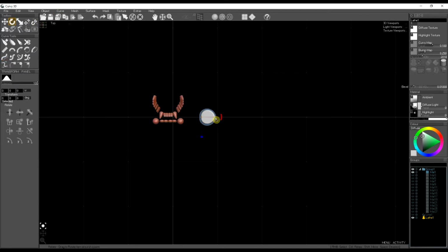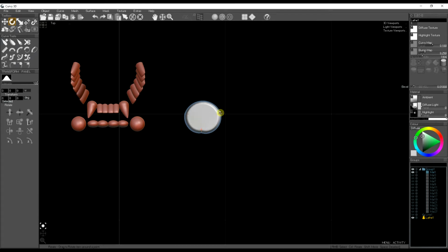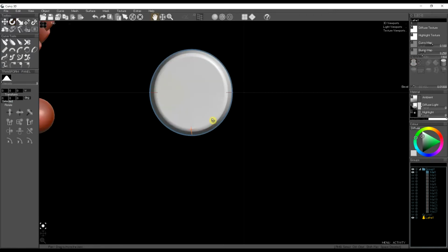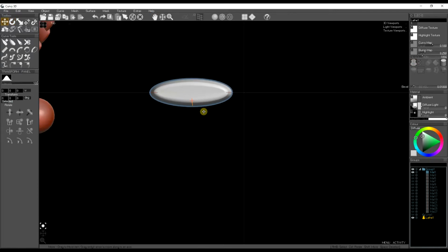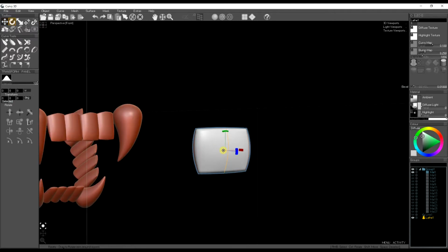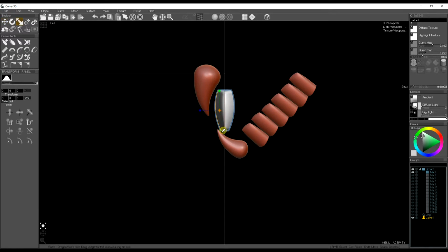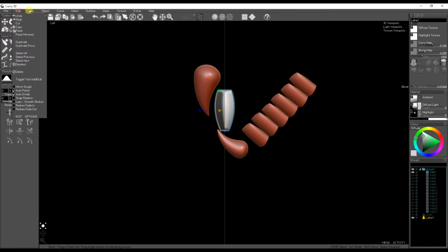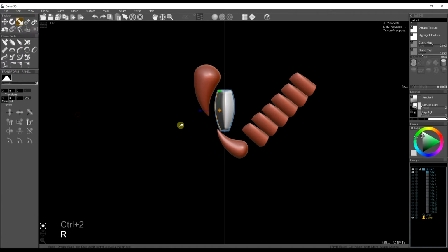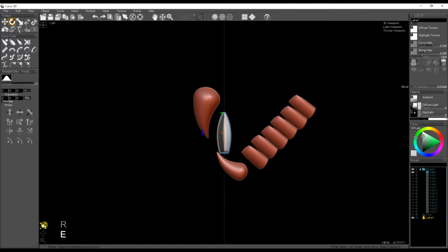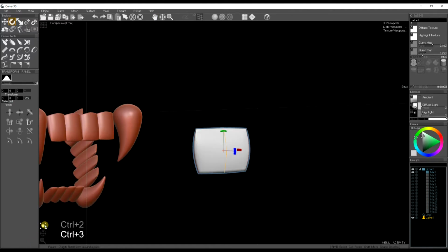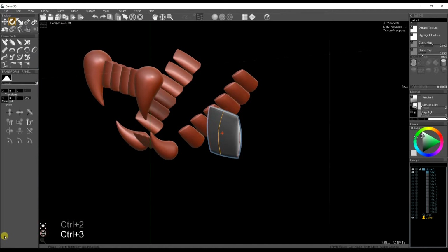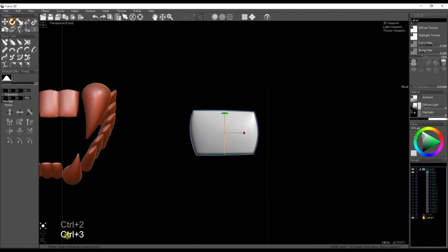and then go to the top view and rotate that curve 90 degrees to the side of the object and turning on lathe symmetry, we now have more control over the profile of the object. And by moving this curve and rotating it into place, we can make the tooth quite sharp on the top. Again, all the curves are still editable, so it's very simple to tweak the shape.